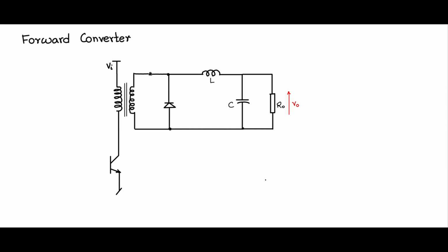So we will put a diode here so that you don't have a reverse current flow. I will make some space and put the diode. So at least now it is safe. Even if this is freewheeling, this diode will not allow a short circuit to happen across the secondary and thereby reflect it onto the primary.